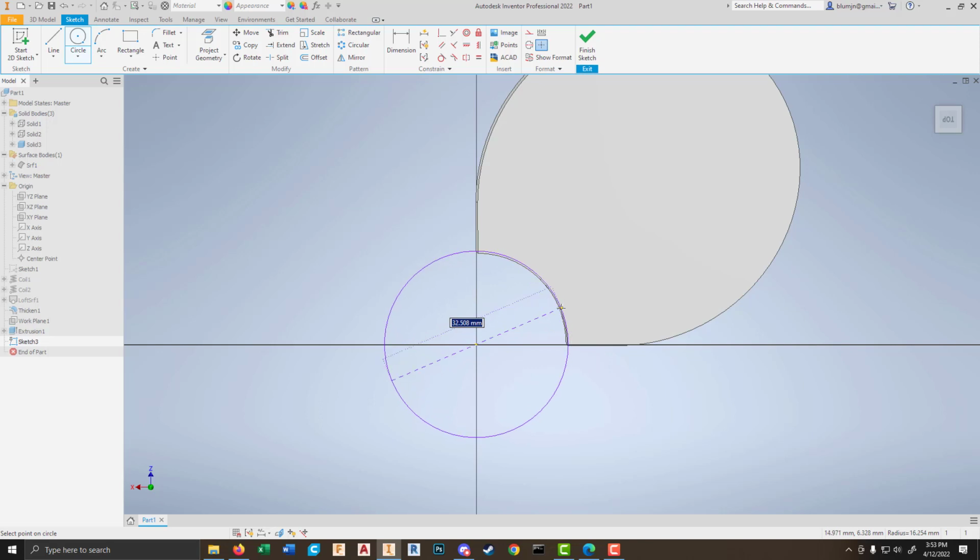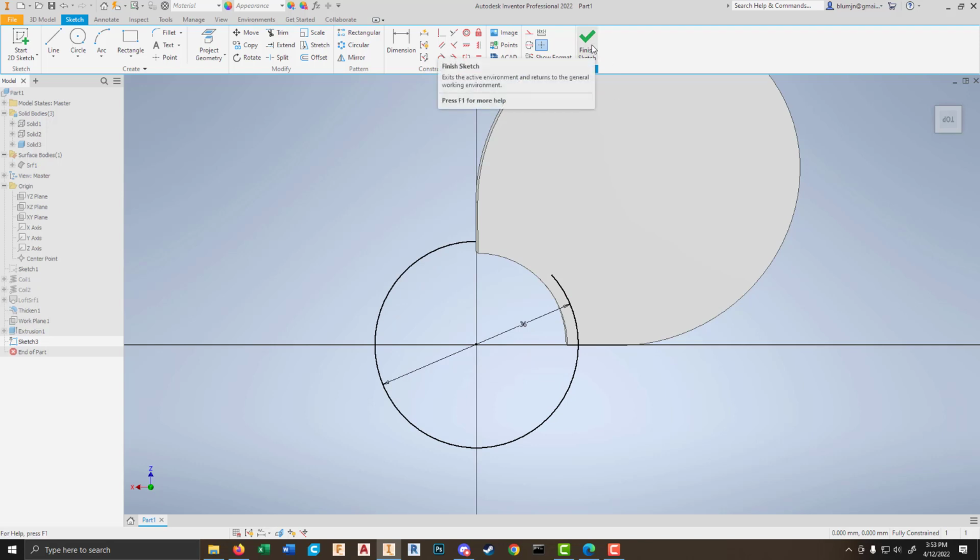And we're going to come out here, and let's go to 30. Let's type correctly and do 32 millimeters out. That matches exactly what our inside is. I think I want a little bit more overlap than that. So let's go ahead and buffer this out to 36 millimeters. And let's go with that. So that's it. That's this sketch.